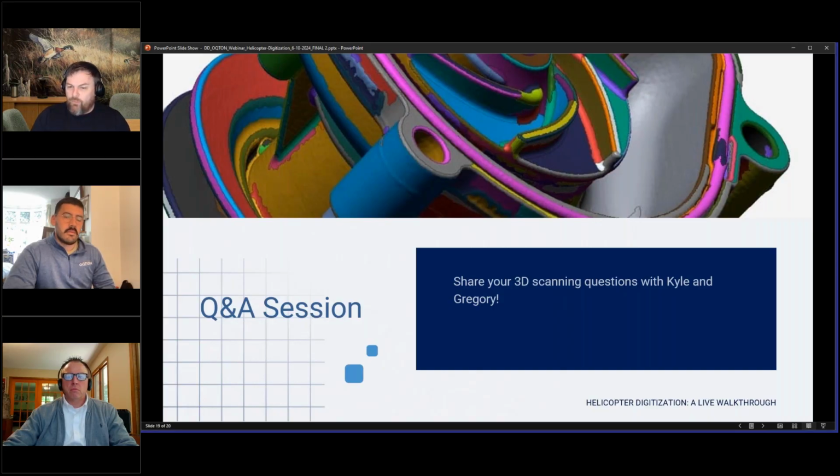And my software has the ability to fit exactly to it, so it would fit and average out and create that 2.97, whatever. And then DX also has the ability to add the design intent. So once I fit that circle, I could then override it and make it 3 inches and infer that it must have been a 3-inch circle.